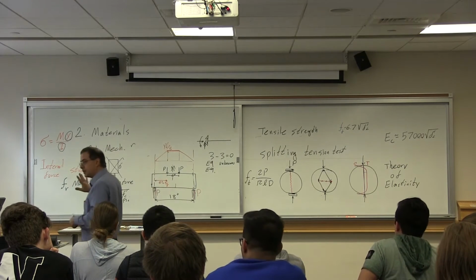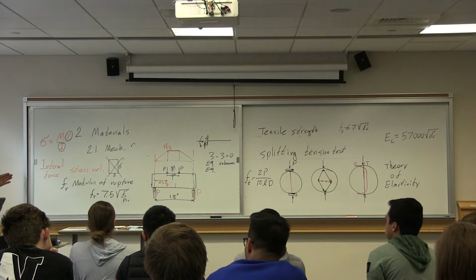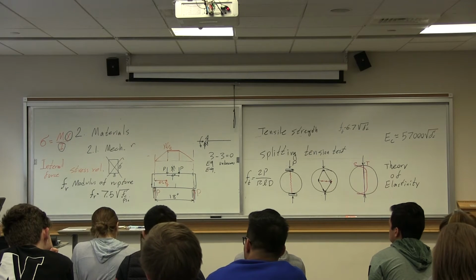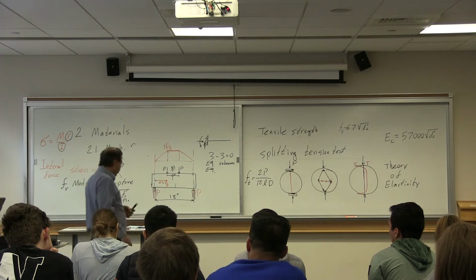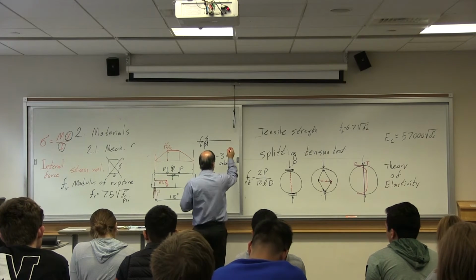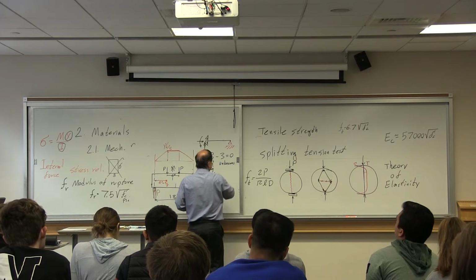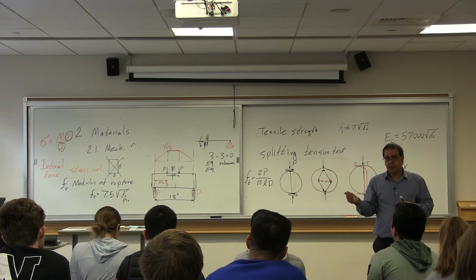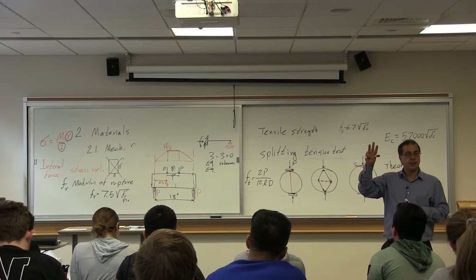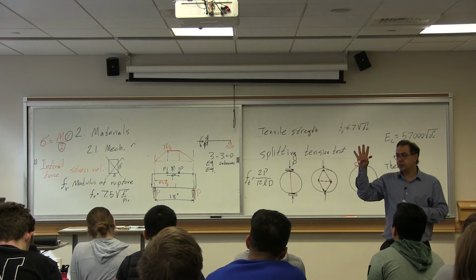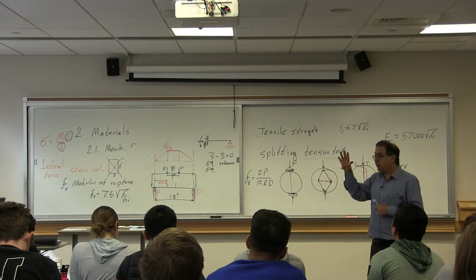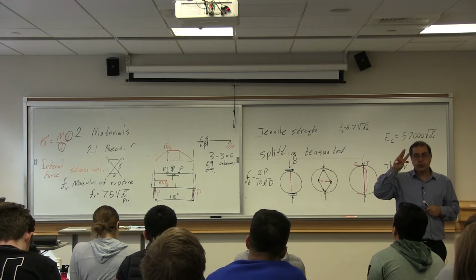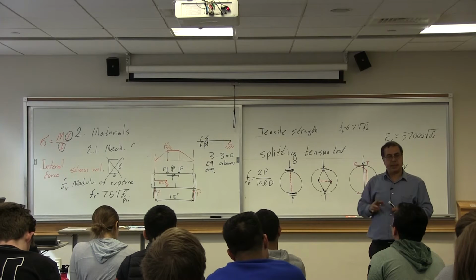In 2D problems, for systems that are rigid, you have 3 equilibrium equations. If now I add this support, now the structure is statically indeterminate because we still have the 3 equations, but we have 4 unknowns, correct? So if you have 4 unknowns and 3 equations, what can you say about that system based on mathematics?